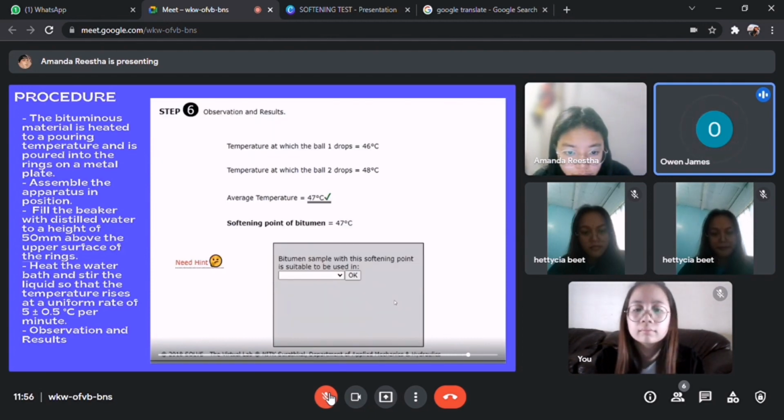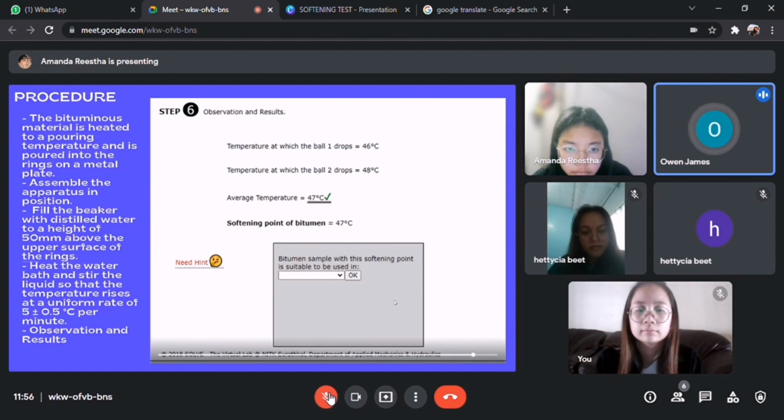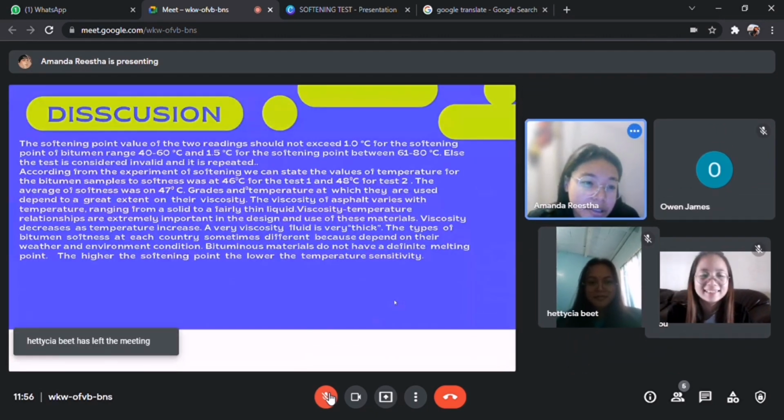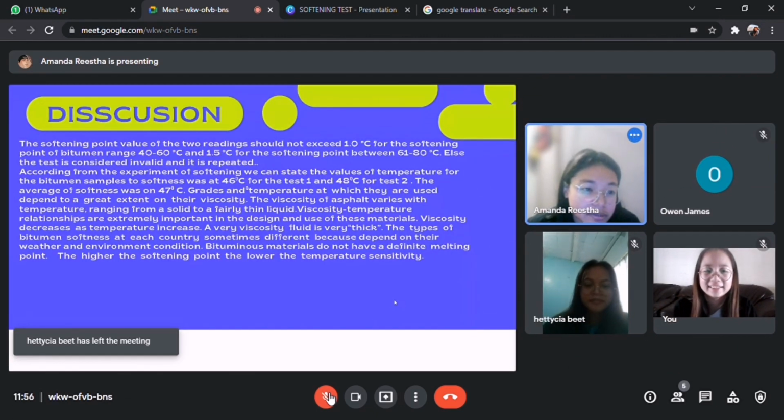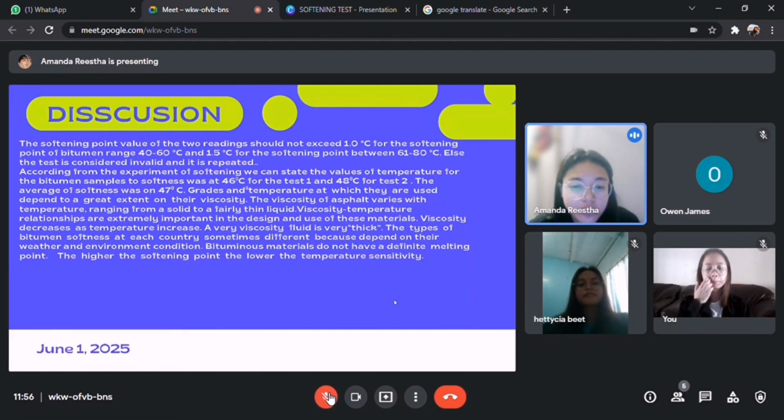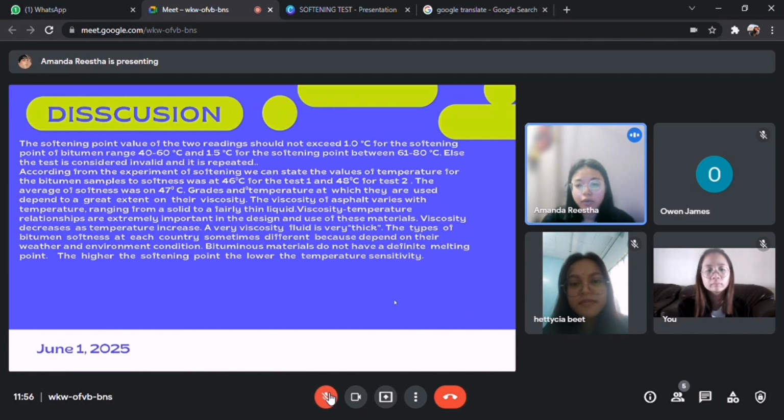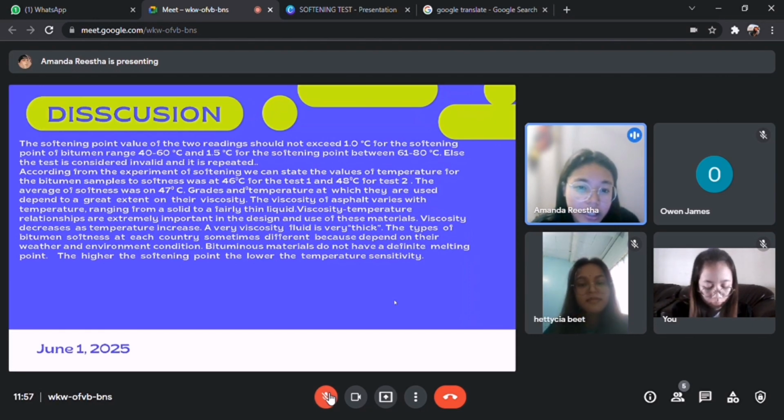For the conclusion, I will pass it to Amanda for the next. Hello, I'm Amanda. I will continue with the discussion. The softening point values of the two readings should not differ by more than 1.0 Celsius for the softening point of bitumen in the range 30 to 80 Celsius, and 1.5 Celsius for the softening point between 80 to 157 Celsius. Otherwise, the test is considered invalid and it is repeated.